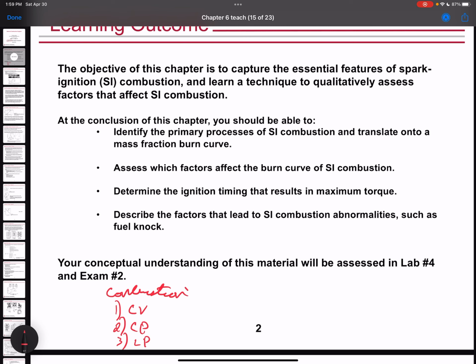We can't just release the spark, for example, and then assume that there will be this instantaneous combustion process where it all happens and we go from, say, a fuel like methane, CH4, directly into CO2 and H2O, right? That's not really what happens. What happens is you have a species like CH4, and it decomposes into various radicals and intermediate species, and these radicals and intermediate species are essentially what ultimately lead to the final oxidation of carbon monoxide to CO2 and hydroxyl and hydrogen atoms to H2O, okay?